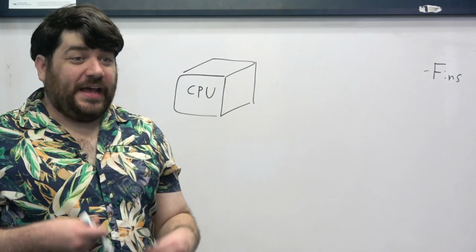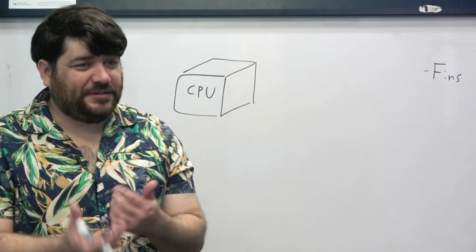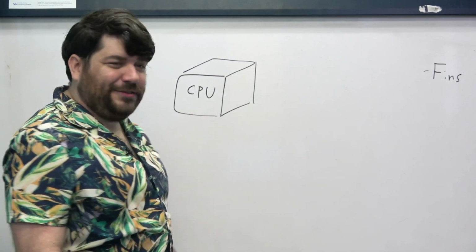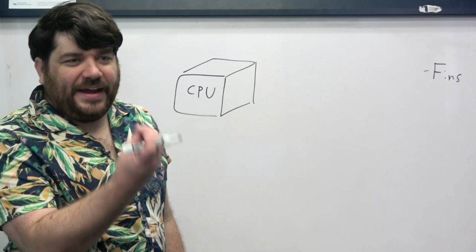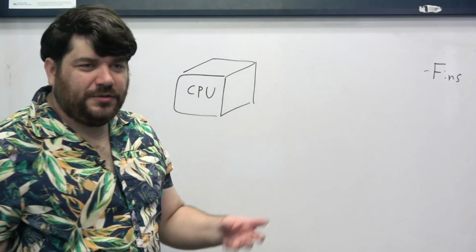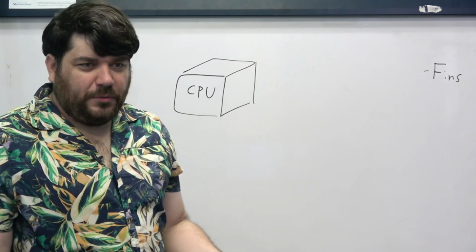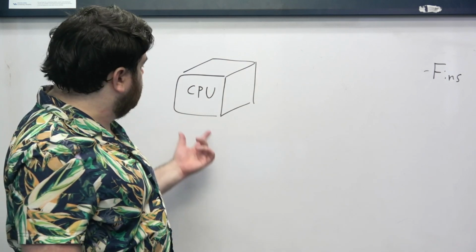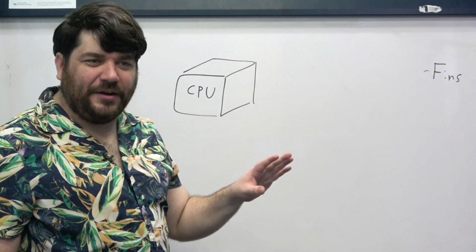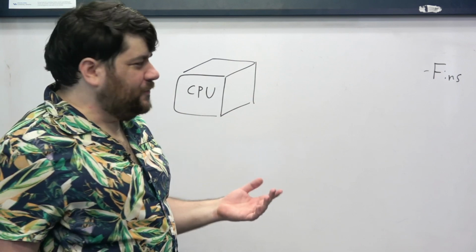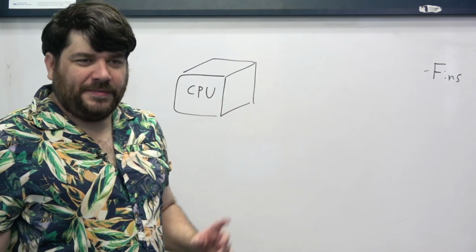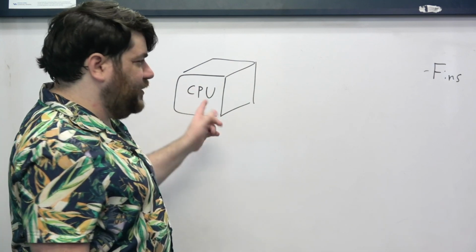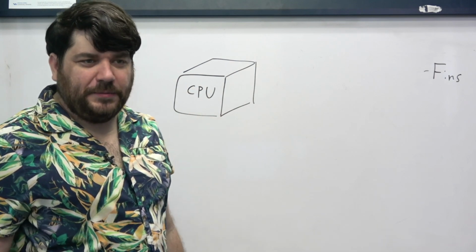That thermal energy manifests in the form of a volumetric thermal energy generation rate inside of the CPU. That causes the temperature of the CPU to increase up until a point where the amount of energy that the CPU is emitting into the air or its surroundings per time matches the rate of thermal energy that's being generated inside of the CPU.